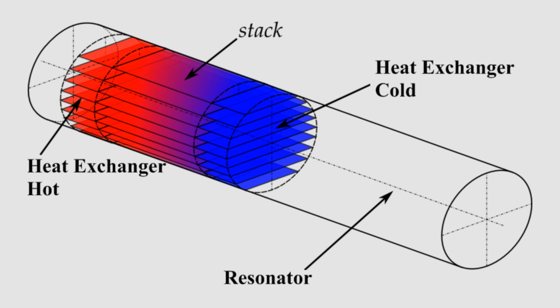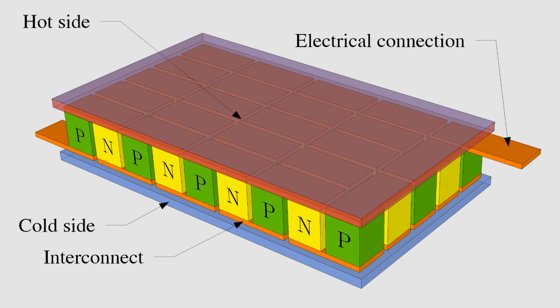And then there are true solid-state heat pumps that are thermoelectric or thermomagnetic. The thermoelectric ones are actually in use for small-scale applications and also some scientific applications, but we mostly know them as Peltier elements for small-scale applications. These have the nice side effect that they can be used both ways. The Peltier element can actually be used to pump heat, that is, if you apply a voltage to the element, a current goes through the element, and one side heats up, the other side cools down, and heat is pumped through the element from the cold side to the hot side.